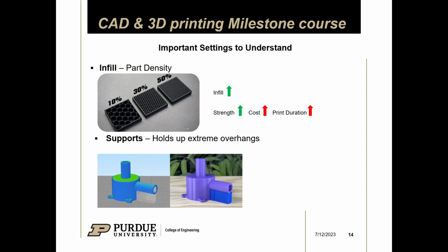One of them has like 2 perimeters and 40% infill, and you can see the density of the cross hatching is a lot more dense. So that typically adds strength to your parts, but in comparison to perimeters, you're going to be getting a lot more bang for buck material-wise by adding more perimeters instead of infill. But sometimes you need a little bit of both.